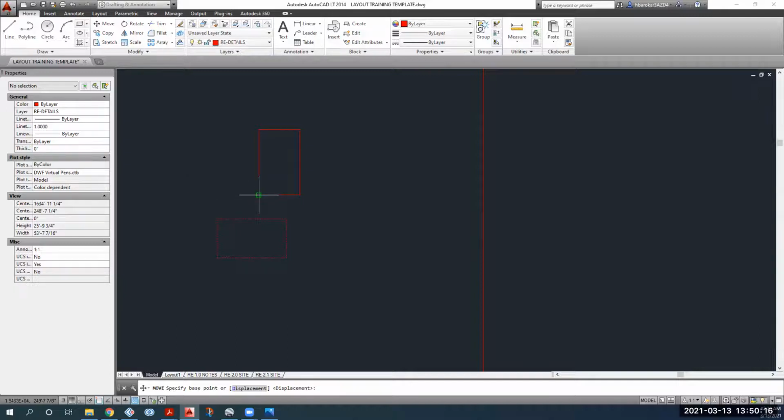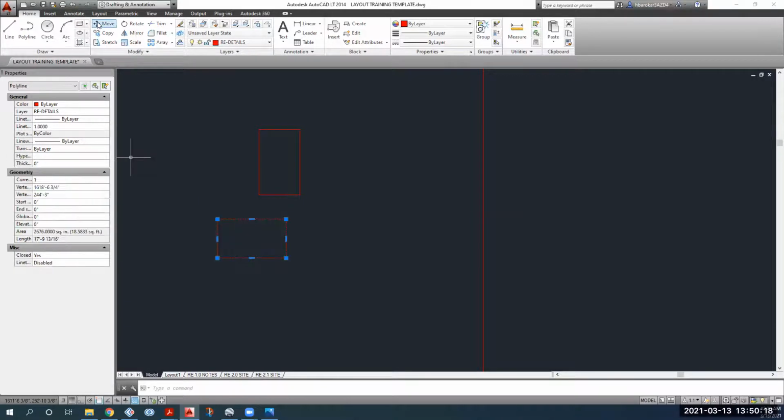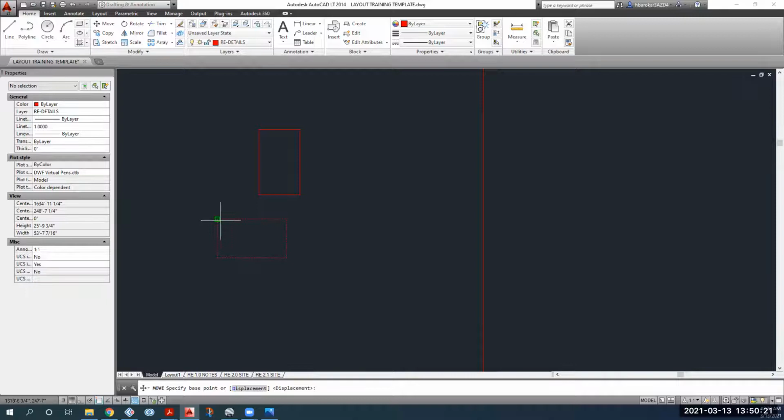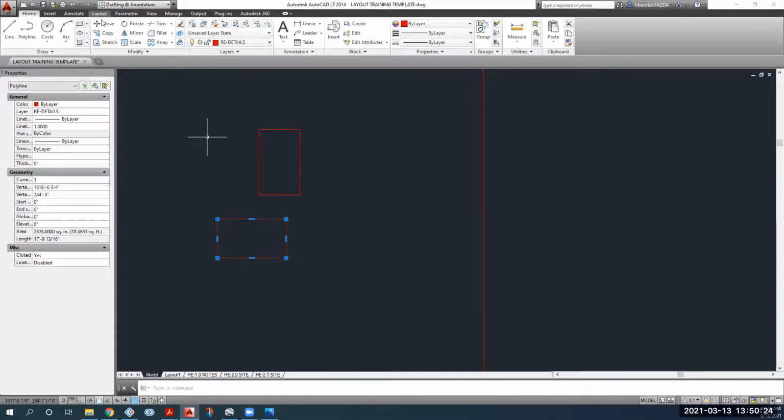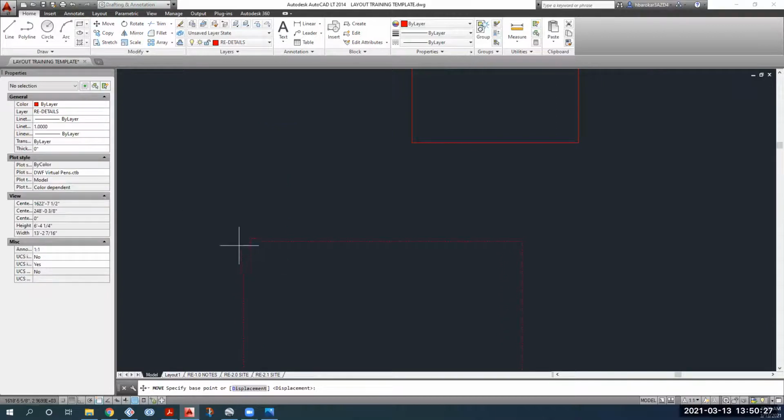So when we are modeling it, we have to keep a 3/8 width between those two modules. Now AutoCAD has this thing where you can move things in a certain orientation. So I select this object, I click move, and I go to this corner. I hover over this corner and then move my cursor up, so it gives me an extension. Now I type in the extension that I want, and this is going to be 3/8 of an inch. I press enter. You see there is this little gap between the crosshair and the model. Do you guys see it? Okay, so I put it here. So now this and this have a 3/8 gap.